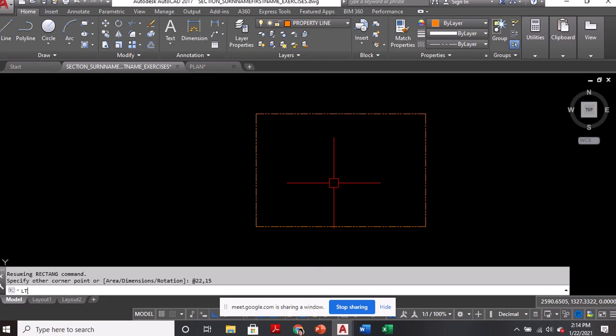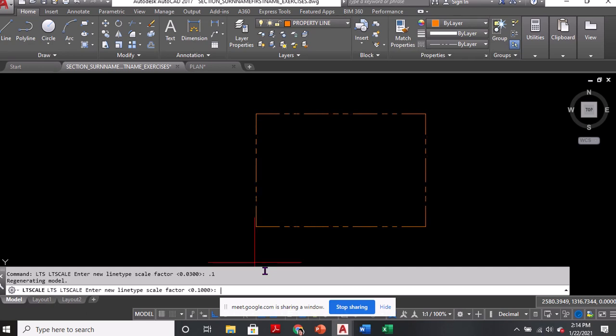Now, there are times na kahit na yung property line yung naka-center line or naka-hidden, minsan lumilitaw siya ng continuous. Okay? You have to check your line type scale. It should be 0.03 or minsan hindi tayo para-pareho ng amount. It might need a bigger or a greater or a smaller value than what is given dun sa akin. Minsan, pwede yan ng kahit 0.1 lang. Okay? So, hindi tayo magkakaiba. So, paki-check lang po yun. Minsan nasa pagkaka-install yun or minsan nasa desktop or nasa laptop. But for this one, I will be using 0.03.